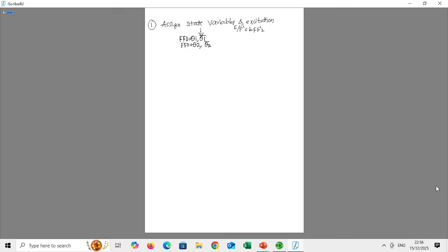We know that when we use flip-flops, the data inputs to the flip-flop like D, T, JK are called excitation inputs. Since two flip-flops are there, let's call D1 the excitation input for the first flip-flop and D2 for the second flip-flop. Now we have finished the first step in the analysis of synchronous sequential networks.